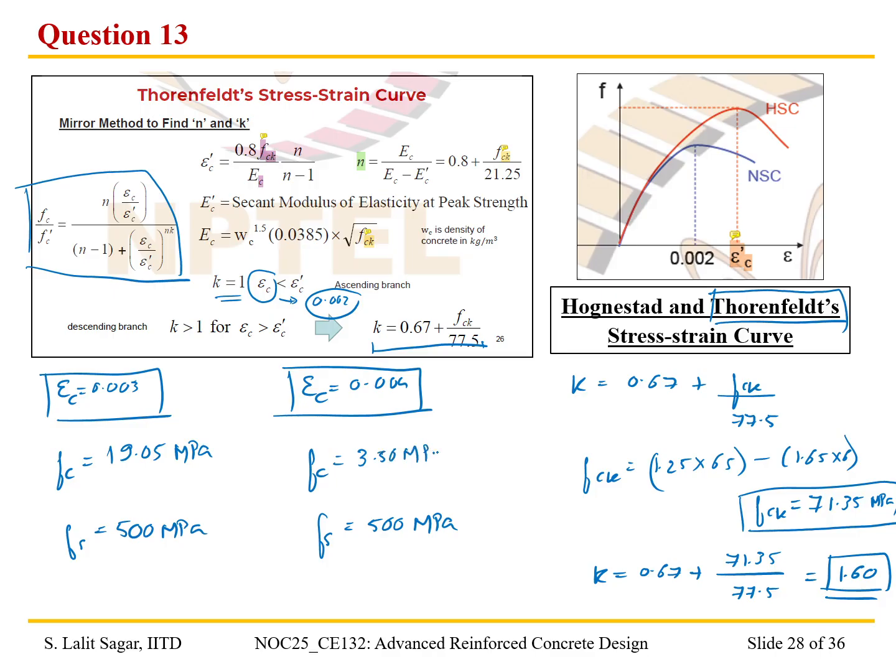So as we have seen in the normal strength concrete, usually at epsilon c is equal to 0.004, it tends to drop off and become 0. But in the high strength concrete, even at the high strain value, it is able to preserve some of its compressive strength. Okay, so from this, we know what is the governing equation for the axial members.